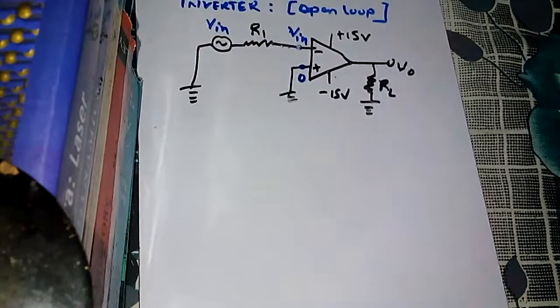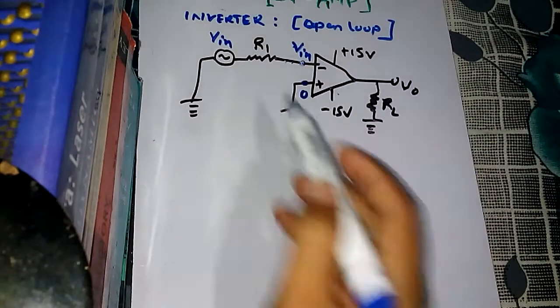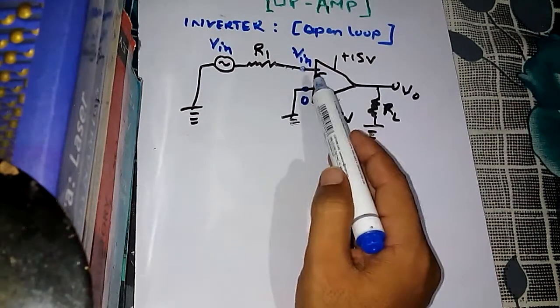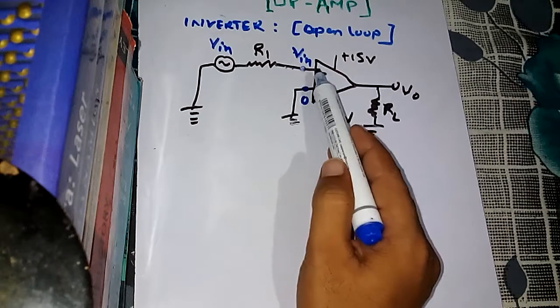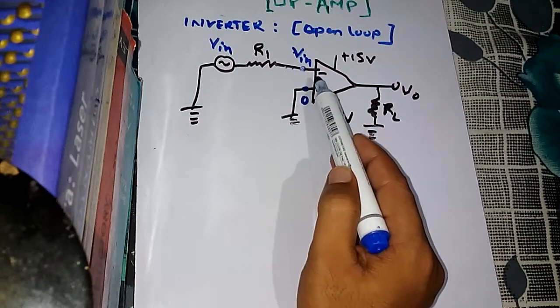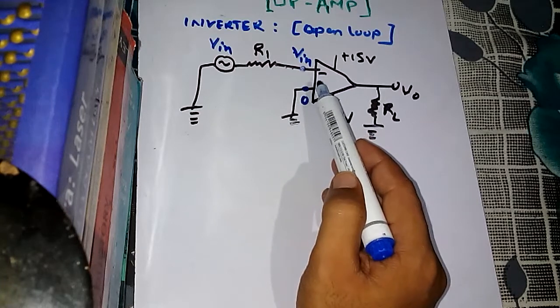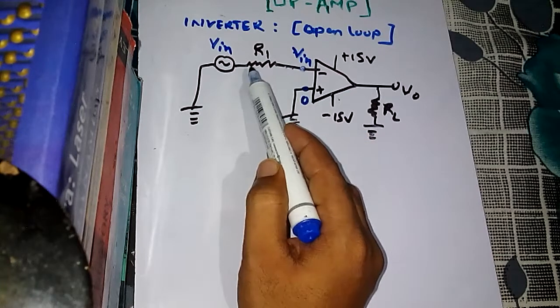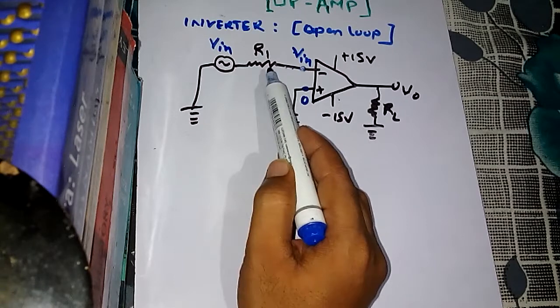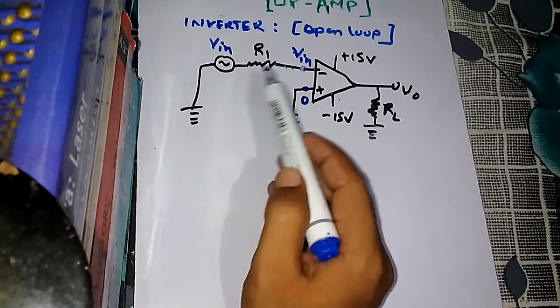Now, in regard to the operational amplifier, you have to be a little patient about what is the case in our operational amplifier. We have told that here there is an infinite input resistance, and because of this infinite input resistance, the voltage drop across this resistance is almost zero. Why are we saying this?